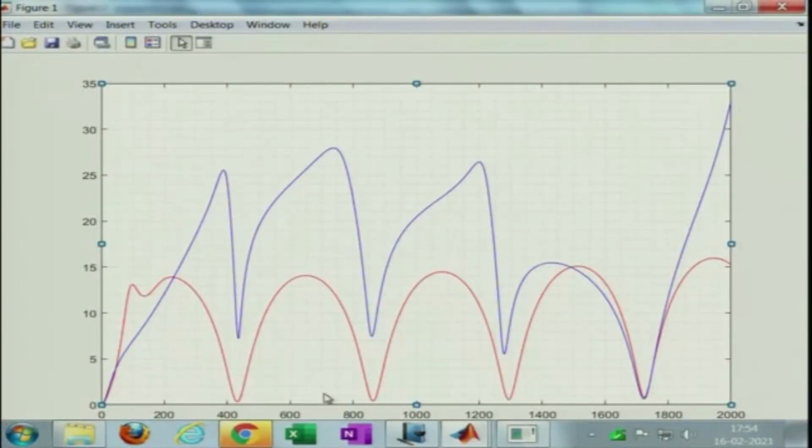So, basically the point I am trying to make is that the mean flow definitely reduces the attenuation peaks that are present, but it still tends to produce increased attenuation at the frequency range where normally the trough would occur. So, the mean flow will have only a small effect on the end correction, but in the presence of mean flow it is a bit difficult to tune the performance, at least in the context of one dimensional analysis.